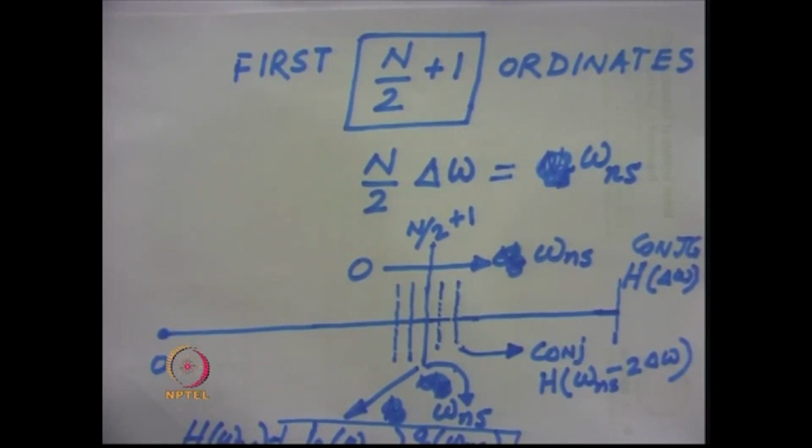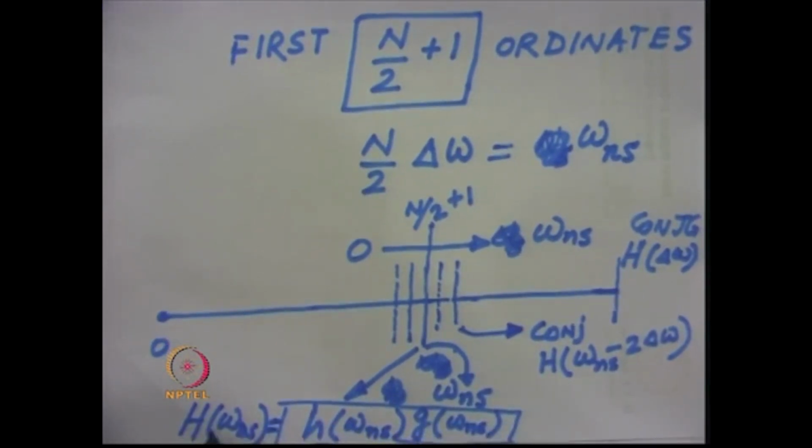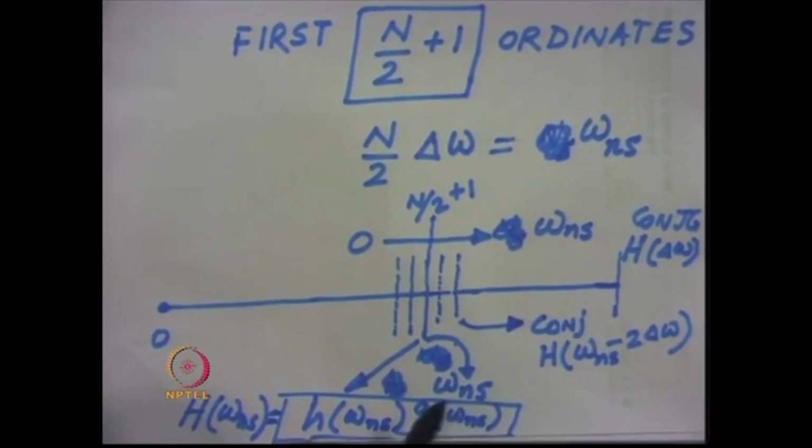The H omega can be obtained from the equation that I had shown before, that is k minus m omega square plus I c omega and the inverse of that gives you the value of H omega. So, once we get the multiplication of these two quantities, then this is given as an input to IFFT.